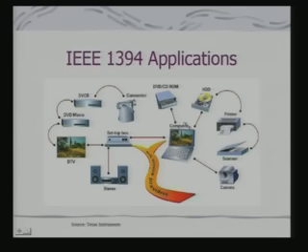If you look at the whole application, this is a scenario likely to be realized through your IEEE 1394 connection, and all these are examples of embedded systems, other than possibly a computer, which is a general purpose computing device. Your stereo can be connected through IEEE 1394 to a set-top box, which gets connected to your DTV, digital TV. It can be a DVD movie player, a camcorder, or even a separate hard disk communicating with the computer via IEEE 1394 connections.